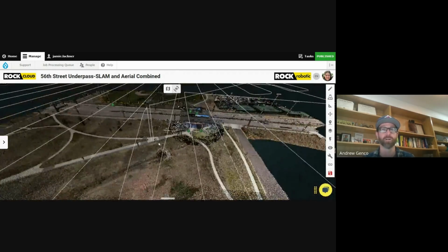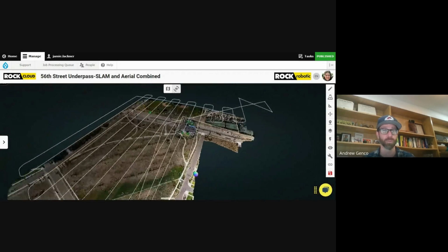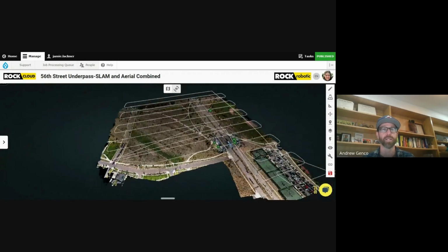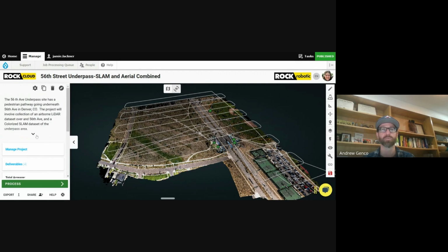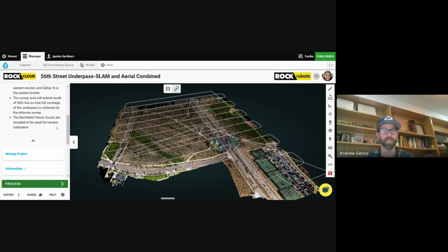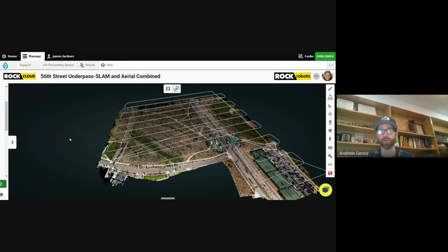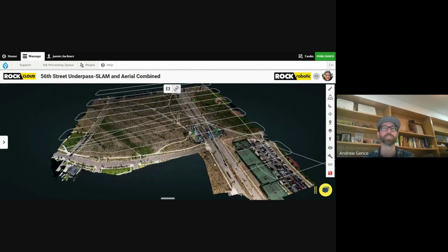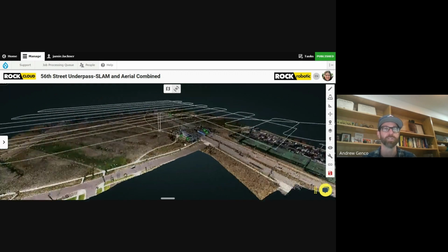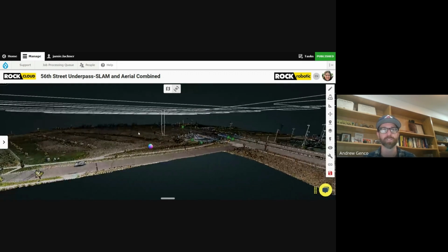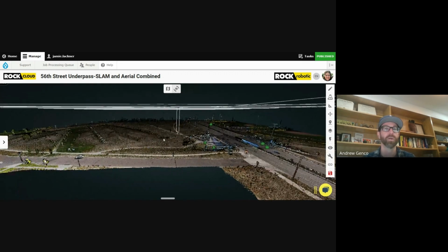Then we focused on our mission parameters based upon the goals. For survey grade deliverables like we were interested in for this project, we recommend flying at 45 meters altitude, 4 to 5 meters per second with 50% overlap. As I mentioned, we reduced that altitude to 37 meters for this specific area, just due to the topographic variation that was present and to kind of play it safe.